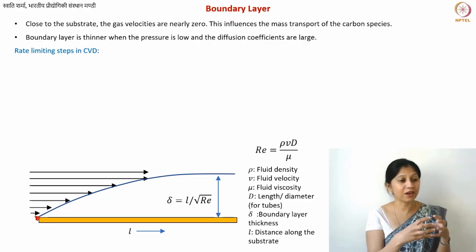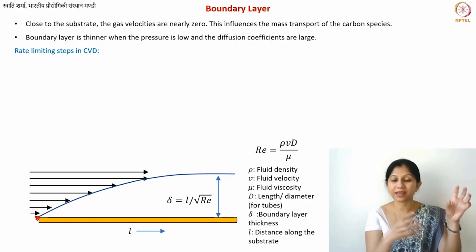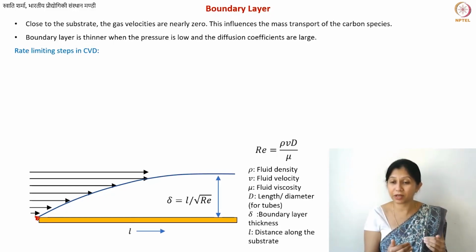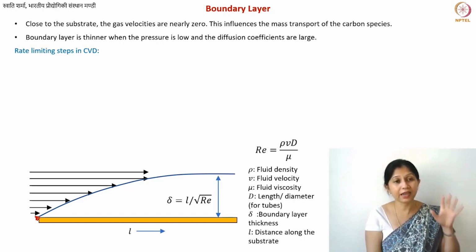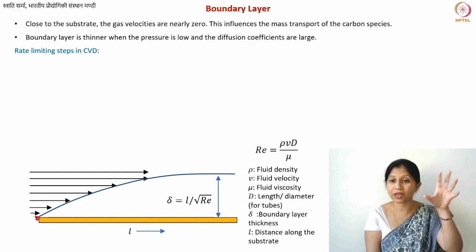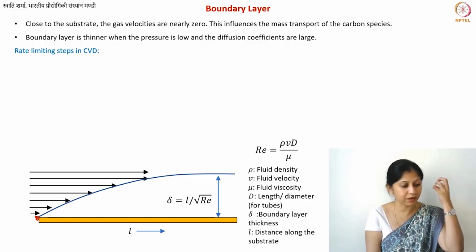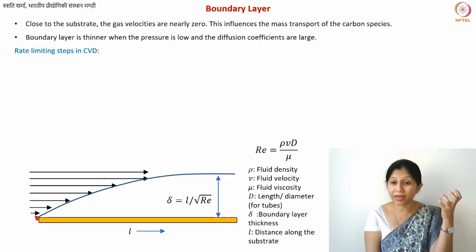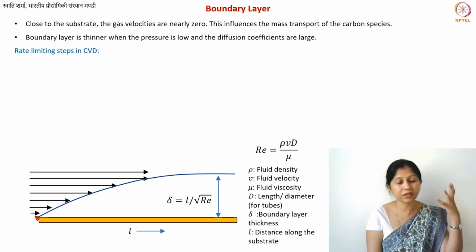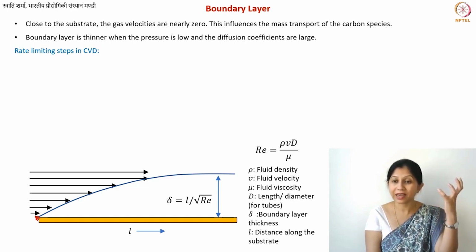So basically your reactants, maybe there are two gases A and B, they are forming some sort of a compound which is C, and then you're getting that C deposited onto your surface. In that case, here the reaction between A and B is very important to you. Here you need to manage, or optimize, the concentration of your reactants and the residence time and all of these things. So in certain cases, the process in the gas phase can be your rate